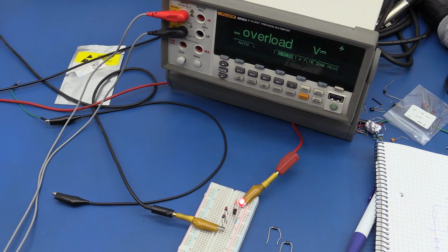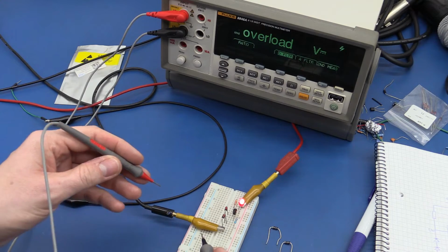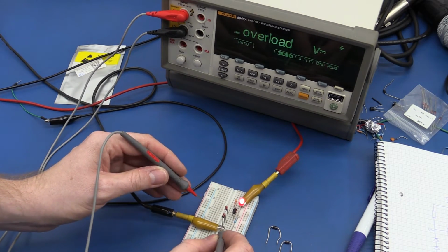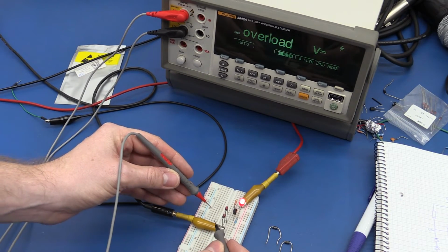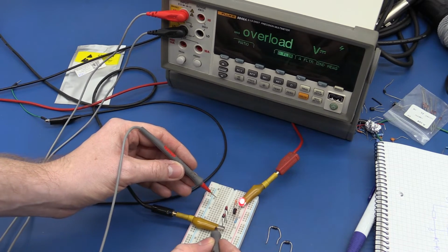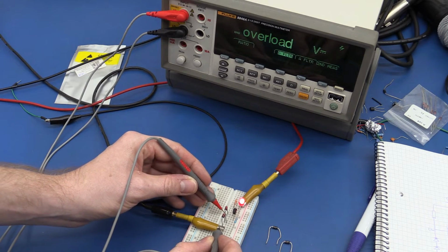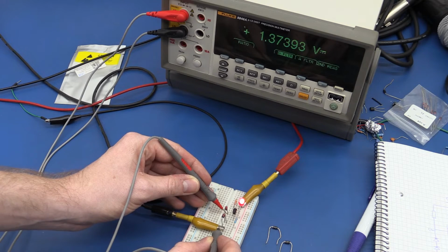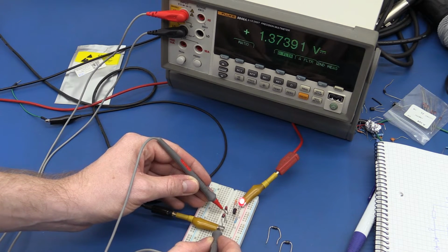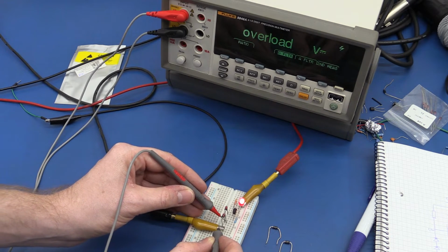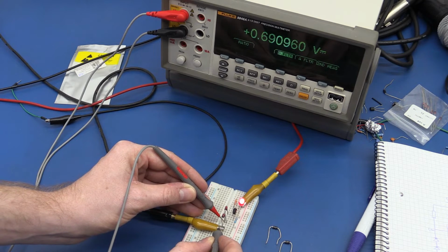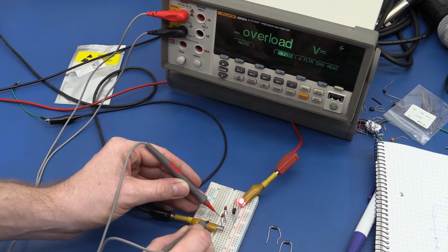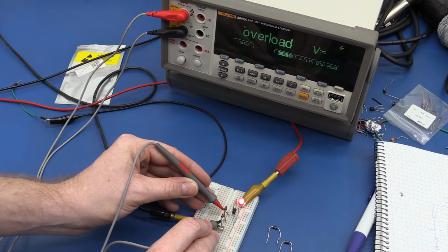So I hope you will be able to see everything at once. And if we start by measuring the voltage drop across the diodes here, we expect 1.4 volts. And we almost get that. We can measure the individual one, and that's, you see, not quite 0.7, but it's close enough.